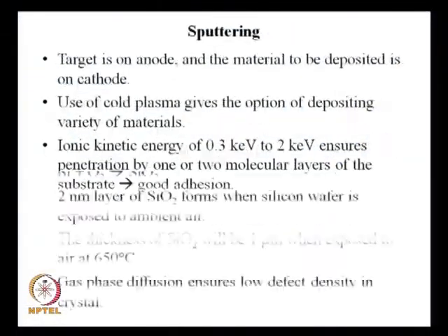So, if somebody wants to make a deposition to make an electrode at one particular portion on the channel wall, he has to resort to either thermal evaporation or the other technique, which is sputtering. Sputtering means instead of heat, you would be using plasma. That means you are providing the energy in the form of electron volts. So, these are the techniques that we talked about regarding deposition.